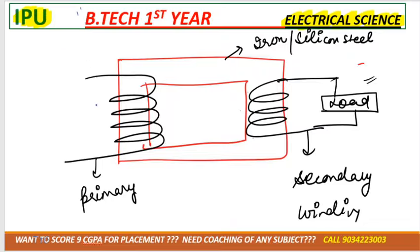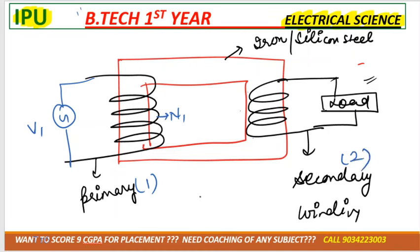Now see, here the primary winding is connected to the AC supply. Here the voltage is V1, the number of turns is denoted by N1, all the primary quantities are denoted by 1 and all the secondary quantities are denoted by 2. Here the number of turns is N2. The current flowing in the primary is I1, the current flowing in the secondary is I2, and due to this current, flux is induced.